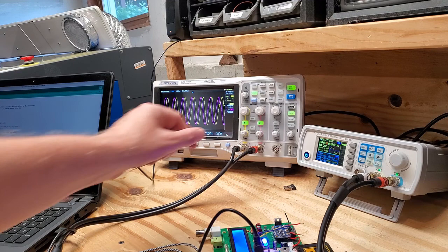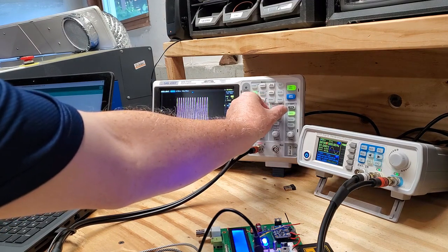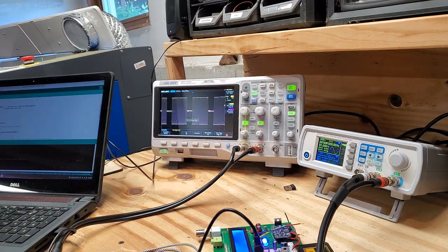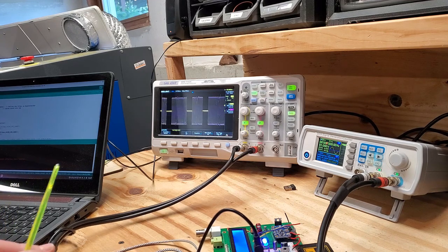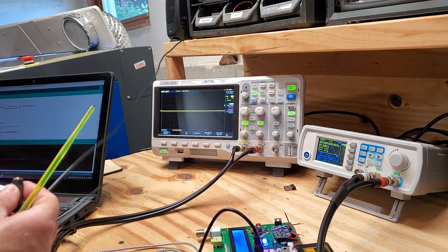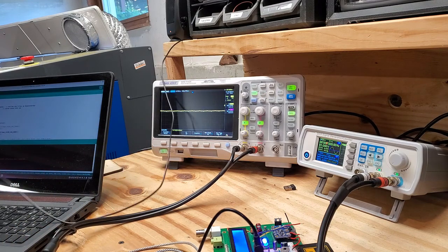And there you can see what we'll see when there isn't enough processing horsepower to do all the computation and keep the I2S stream going. So you can see the significant breaks in the output here. And if we just go to the speakers, if you don't have an oscilloscope, you can hear what that result is like.